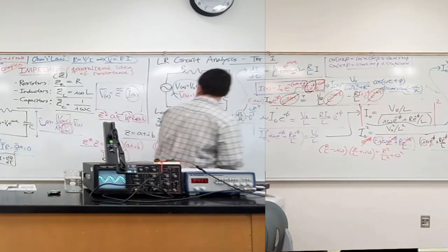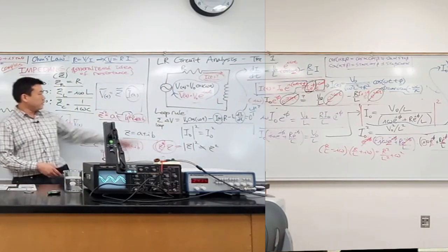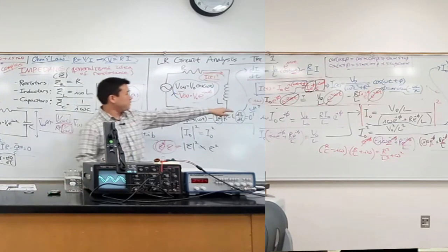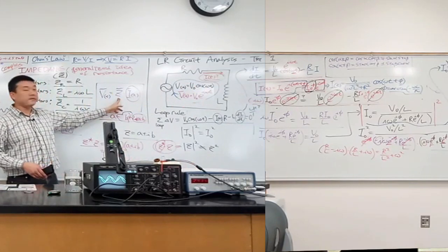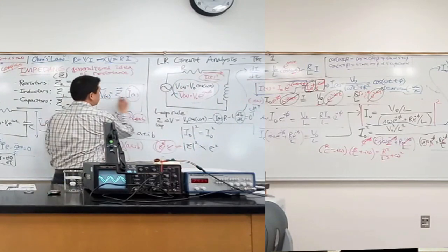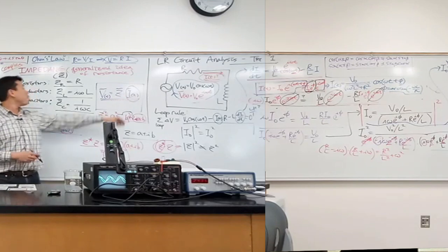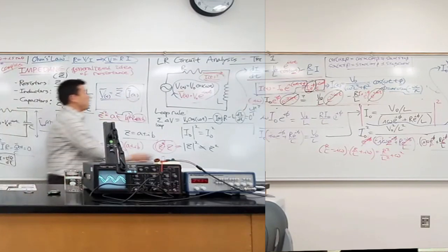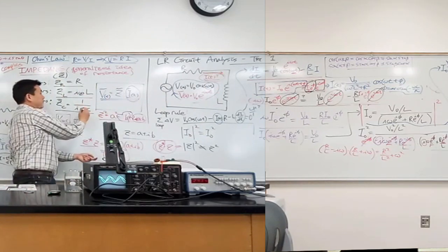What I'm going to do for the remaining 30, 40 minutes is this: with these expressions for voltage and this expression for current, I can simply use this, and it'll give me the correct result. This is really the point of defining these complex impedances this way. These are defined in this way to make this expression true when you are driving with oscillating voltage or current, which is necessary to have a well-defined omega.